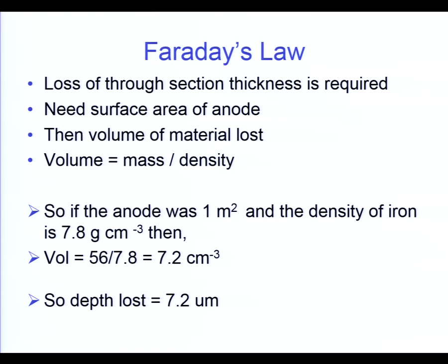Actually, that's another point. Densities are usually in grams per cubic centimetre. I know that multiplies straight up, but well, yeah, kilograms per cubic metre, 7,850. So would you really want to take it up and then drop it back down? No. It'd come out with the same answer in the end, it's true, but I think it's easier to do it that way. Okay.